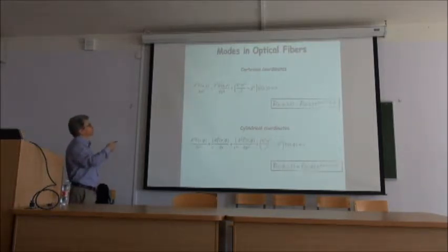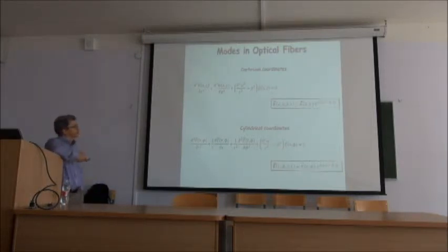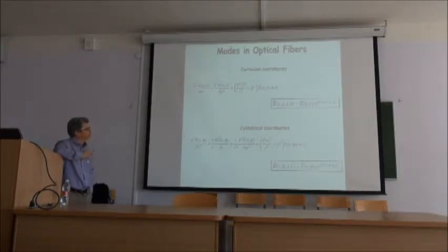Essentially, to do the math that we've done with the waveguides, we can take the previous equation that we've been using. This is the Helmholtz equation, which came out of the wave equation, and we wrote it in Cartesian components, x and y here. We had a component for z, so that's the solution we attempt to implement.